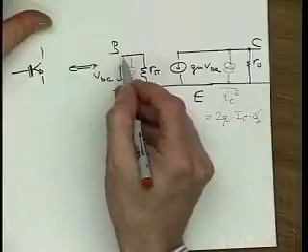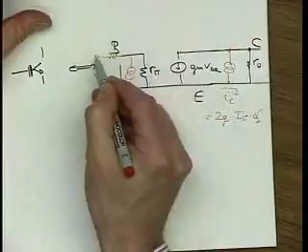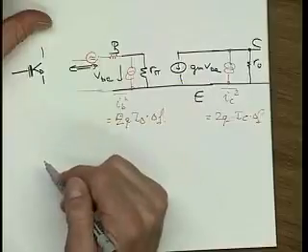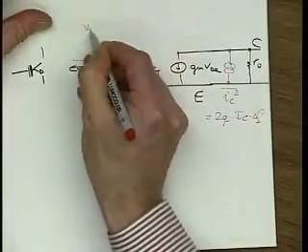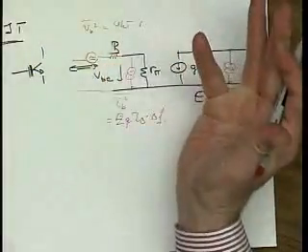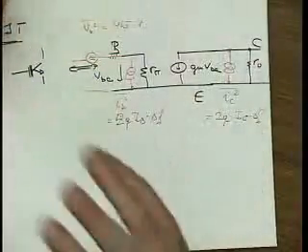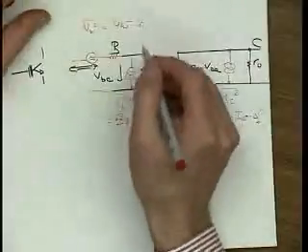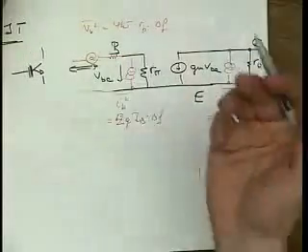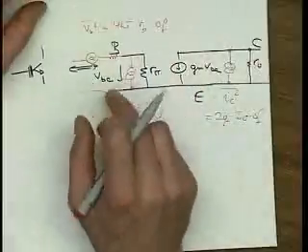In bipolar transistors, often the base resistance, there's just extrinsic base resistance, and its noise contribution, probably most sensibly modeled by a noise voltage source, is significant. So that's VB square is 4kT times, that's just the resistance of tying into the base, right? And there are all sorts of fabrication tricks, poly emitters and so on, to make that small, times delta F. But base resistors in the hundreds of ohms or so sometimes, or at least older technology have that, and then that can be a problem, right?